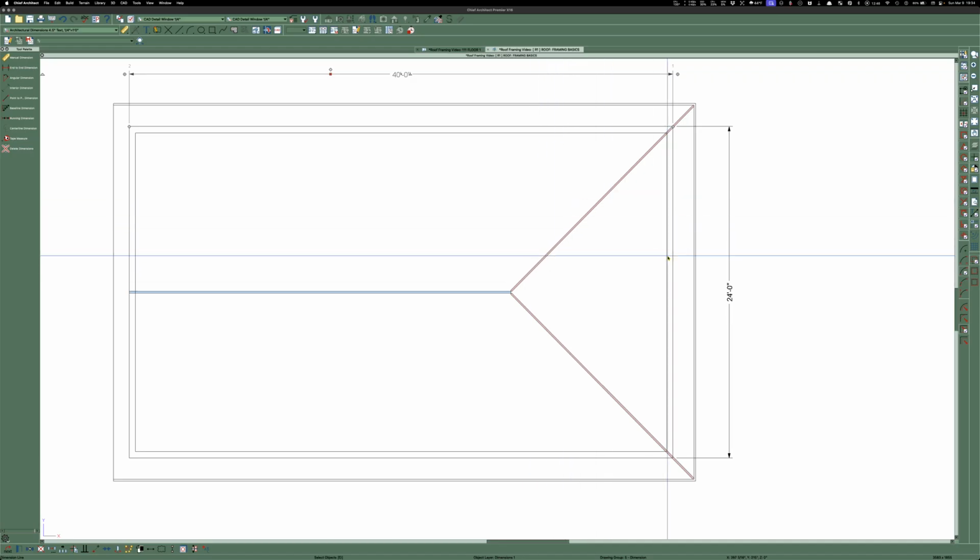And then I've had guys, it was kind of funny, because you have to string these straight, these hips or valleys or whatever, ridge, all of it, just to make sure you're putting your jacks in correctly and not causing a big bow that'll be seen through the shingles. But I also like to lay out the hips with a plumb line at whatever that diagonal is between each rafter. And then I can tell the guys, start in the middle, put your jack down here, and then slide it along until you reach the layout and put a nail in it, tack it.